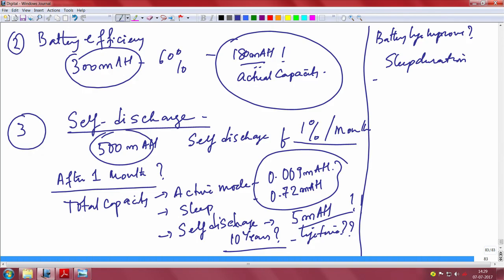One nice thing, in terms of the theory that I spoke to you about, how you calculate battery life and all that, is that you can also do all of what I said in the lab, and you can capture all this with a simple current probe and an oscilloscope, okay.